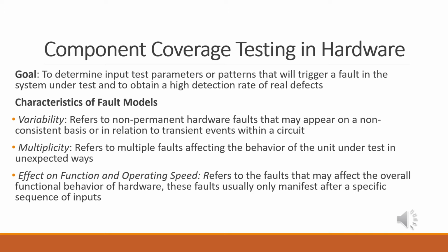Nowadays, there are different ways of generating and validating test patterns, sometimes called test vectors, either manually or automatically. Test pattern generators determine test vectors for a given fault model that will propagate a fault all the way to an observable output. In other words, these are called fault simulations.